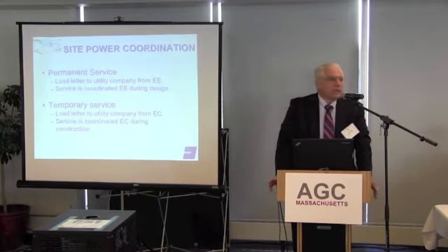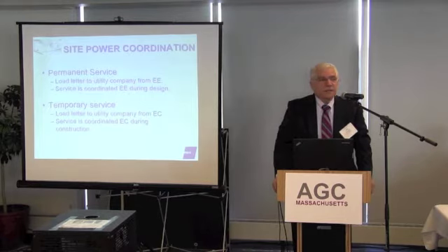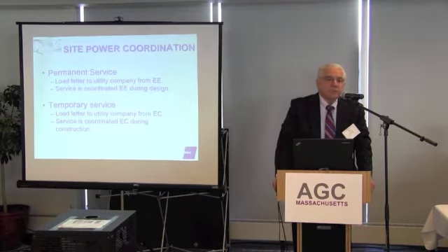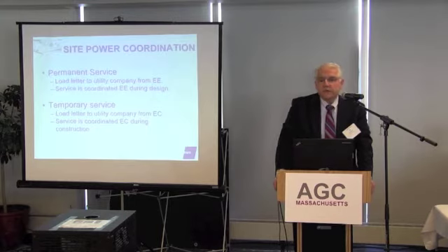Now we're doing a project right now in Seaport where there are 3 tower cranes on the site. Then they have the requirements for welding on the site, which is usually a 480 volt, 100 amp feed. You have the staging that you see traveling up and down the building, and that's usually a 100 amp feed or 60 amp feed, depending on what they have. So, you know, they eat up.